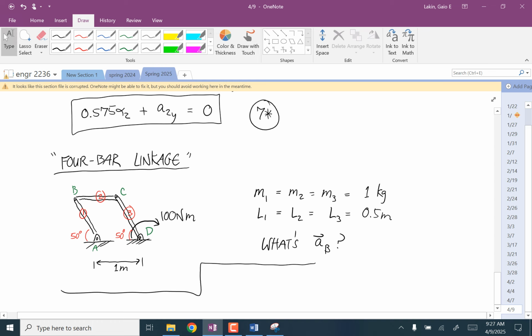Okay, so one of the things that 4-bar linkages do that's useful is as they move, they're defined by a single degree of freedom. Once I give the dimensions of all this stuff, one single angle of these tells you the configuration of everything. And one of the things that's useful for is every one of these points traces out a defined curve.